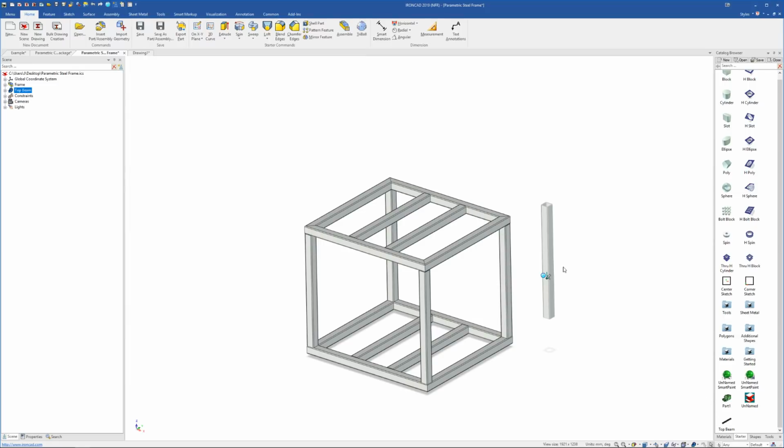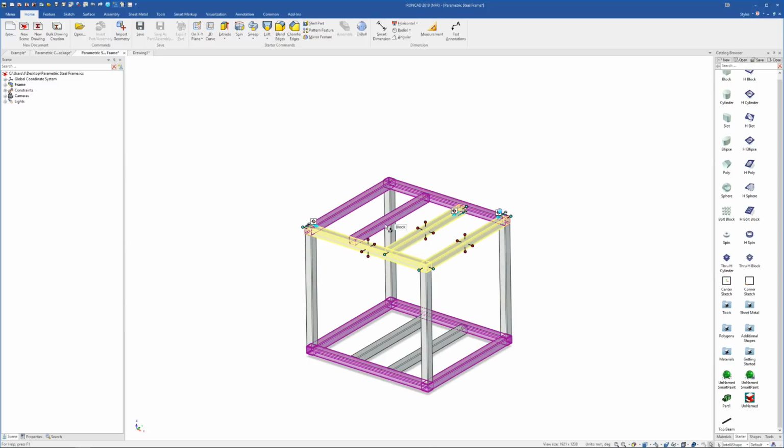It works the same with assemblies at those levels and that sort of thing as well. If you're on the assembly filter, of course, it is important to go back and make sure you change back to the any filter before you start working again, because otherwise it can get a bit confusing. The same thing works for IntelliShapes. If you're just wanting to select IntelliShapes, drill straight down through to those. Again, you can also do that with the Alt key. Sometimes it can be useful here too. Same works for edges and faces and things.